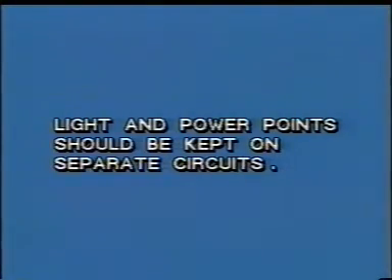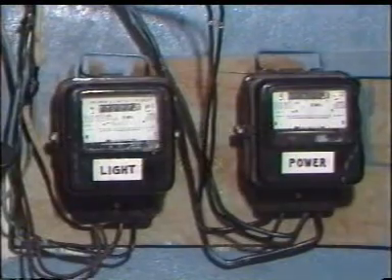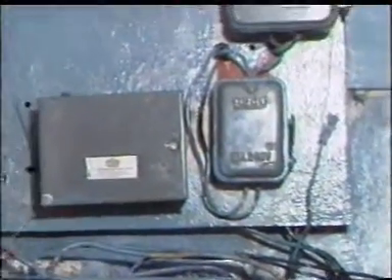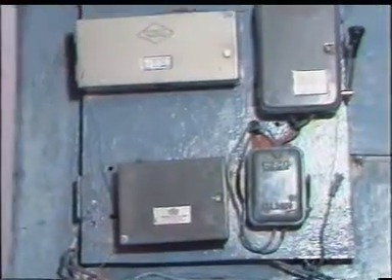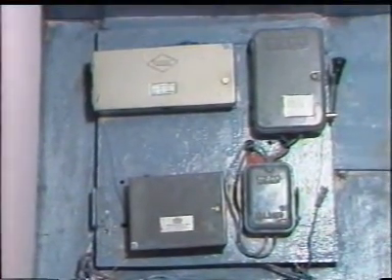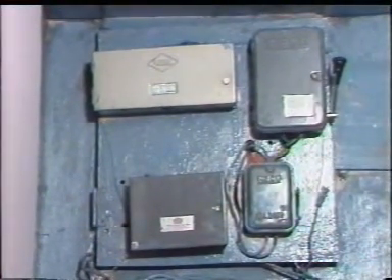Light and power points should be kept on separate circuits. Limit light and fan points per circuit to 10 and power points per circuit to 2.